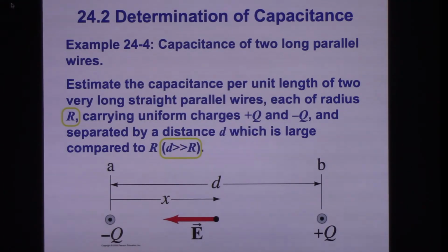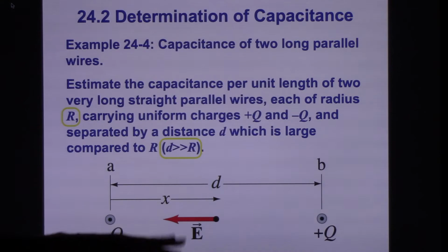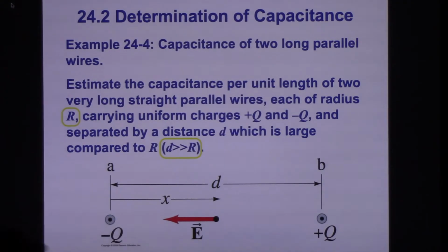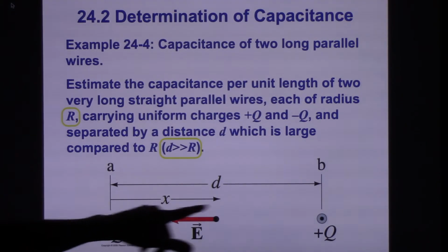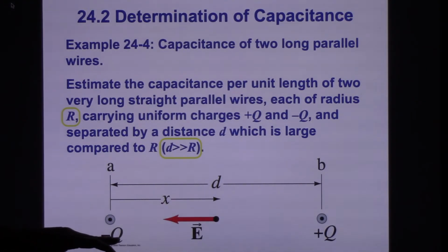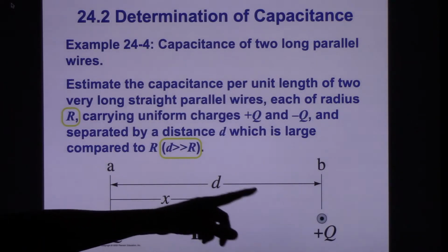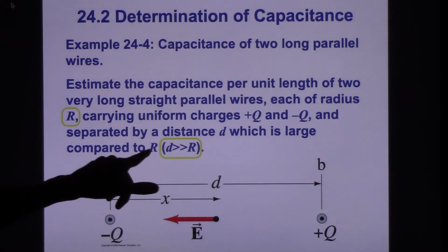So what this one is, it's two wires side by side. So instead of a coax cable where the conductors are running within the other conductor, these are side by side, although there's some distance between them. So I've got two conductors that are running, again, we're going to imagine this is pretty long. How much capacitance is there in two wires, one that's got a little bit of positive charge buildup and the other one negative? So, if I have side-by-side conductors, that also could create a little bit of capacitance in the circuits. So the wires could have an effect on each other. Now what we're assuming here is that the wires are really thin. So this time we're imagining that the wires are really thin compared with the distance between them. D is much, much greater than R.